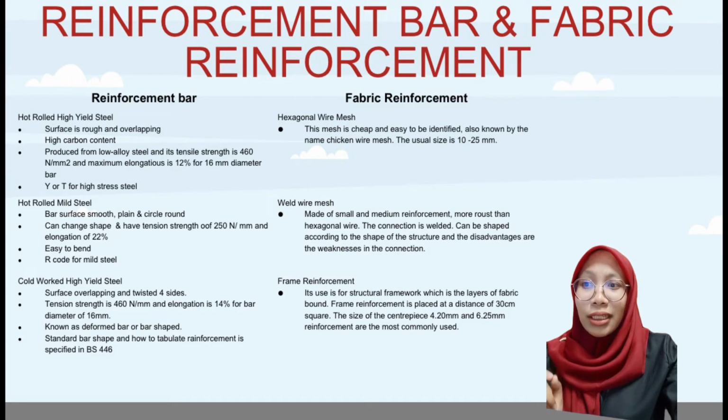The tensile strength is 460 Newton per millimeter square and minimum elongation is 12%, 0.12 for 16 millimeter diameter bar. 4. Y or T code for high stress steel.